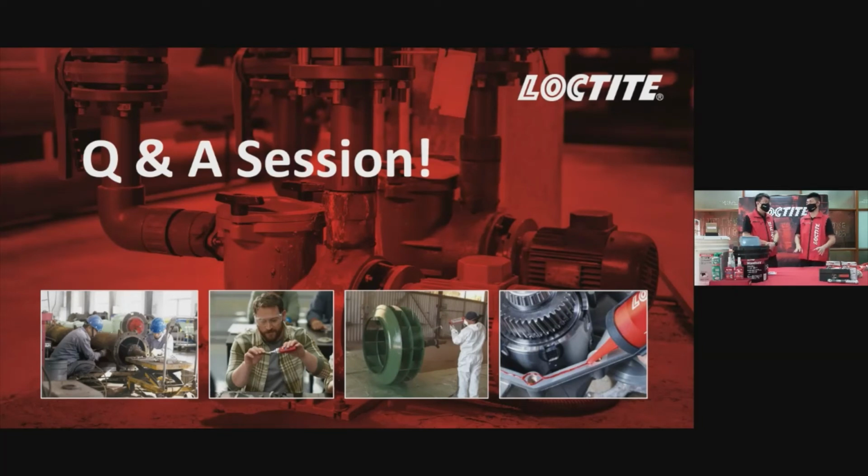And the applications are a little bit different. For example, this wearing compound is useful for coarse solid products. New Wear is suitable for fine solid products. High impact wearing compound is suitable for big chunks of particles or solids. So it depends on what kind of solid we are handling. We will recommend a different type of wearing compound for your application.